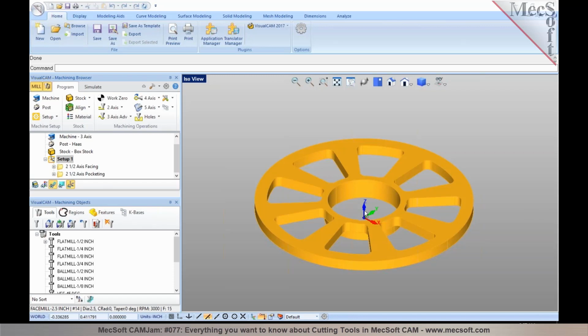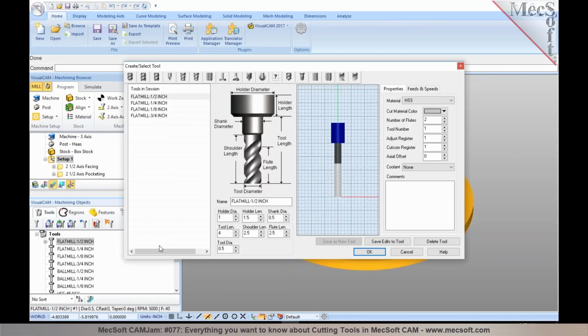So, how can I add comments in the tool? We did talk about this briefly in the early part of the webinar. You can specify comments to be output in here. For example, if I want to output the tool name as a comment, I can enter it right in here. If I want to output an optional M code or a G code, I can add a prefix like $ as a prefix sign, and then specify the code that needs to be inserted.